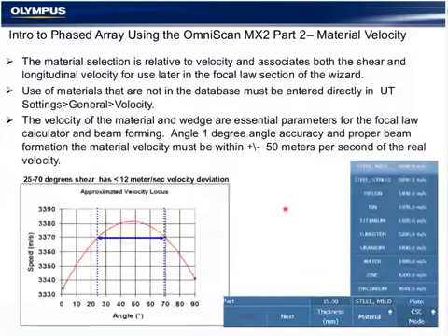The velocity is an essential ingredient and the subject of much confusion for phased array. You either have to know the velocity of the wedge and component, or you have to measure it. We often call the velocity function a calibration, but in fact, you're not calibrating the instrument, it's digital. You're assigning a velocity so the displays will display the data in time correctly.